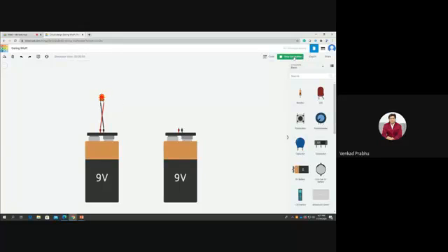So what we have to do, stop the simulation. That is what I told you in the basic circuit, we should not pass that current directly to the devices. So just select that link, which is the positive link, and click delete. I am just removing that positive link, and on the right hand side you can see the resistor. So just put the resistor.